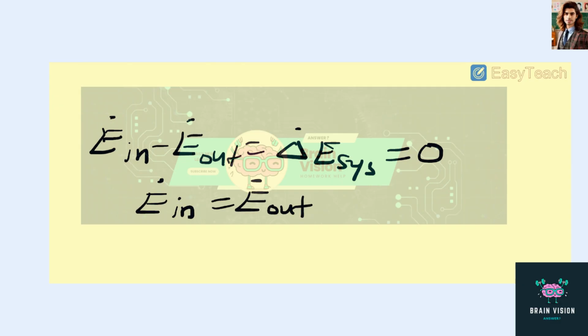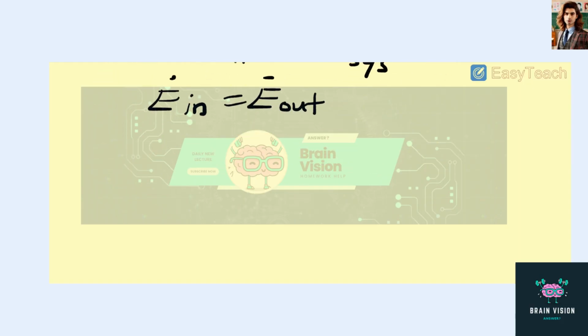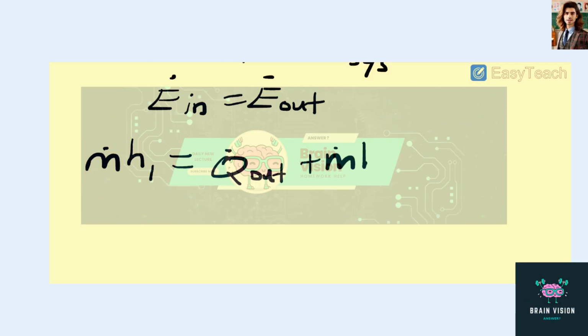Breaking these quantities out, the energy coming in is simply m dot times the incoming enthalpy, and that's equal to the heat that is removed from the chickens plus m dot times the enthalpy leaving the system.